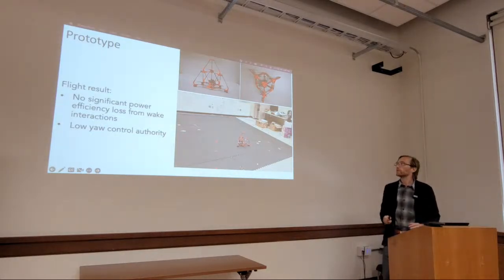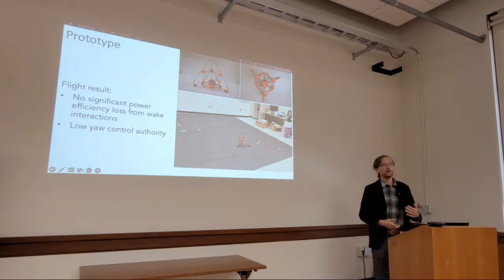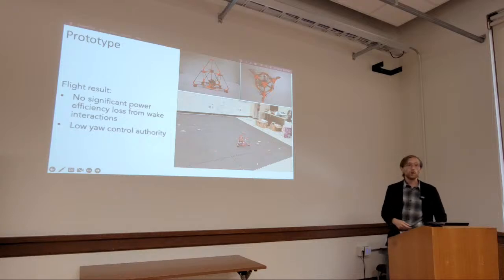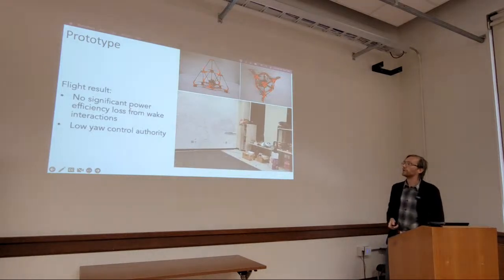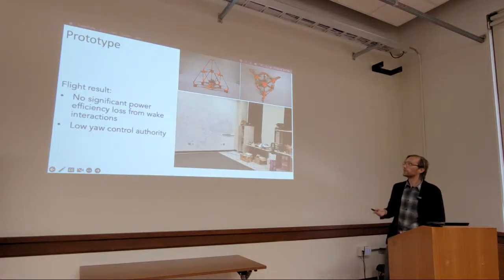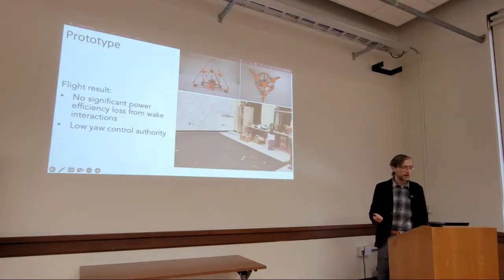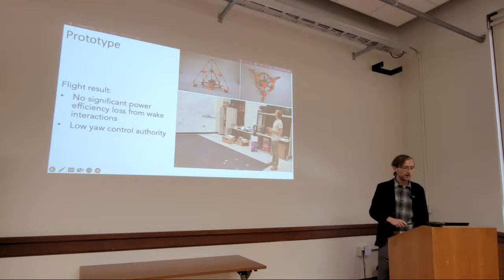The modules are not self-contained. Actually, it's more like just one monolithic quadcopter vehicle, except that the propellers follow the shape of a tetrahedron. What we wanted to verify is that we would be able to fly it. And we encountered some issues, mostly related to yaw control authority. I will not really get into details, but it's not insurmountable.